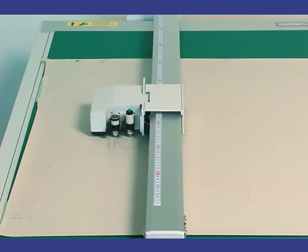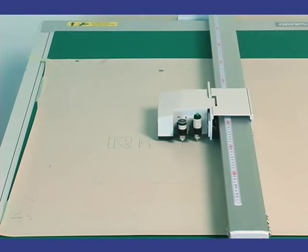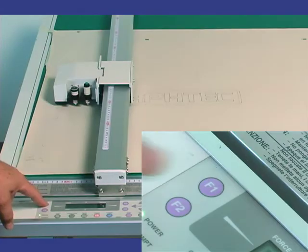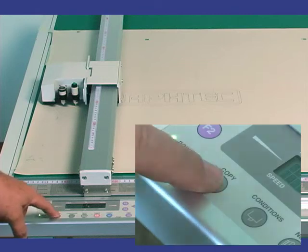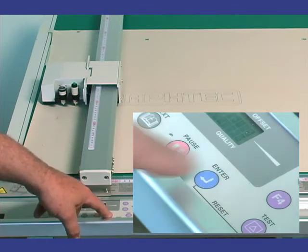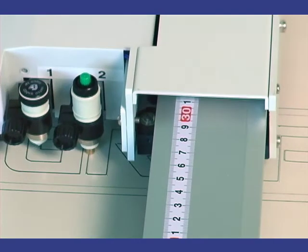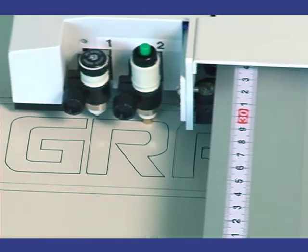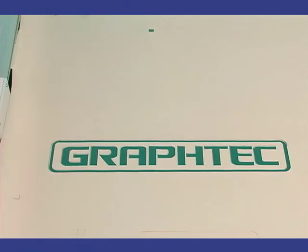What I've done here is I've selected pen 1 and I sent the job. And now it's plotting out the pattern. Next, after the plot is done, I switch the pen heads to the cutting tool. Then I go ahead and make a copy, and I send the job. As you can see, the cutting tool is going right over the pen line. And there we have it. The weeding is easy because we have a pen pattern to follow.